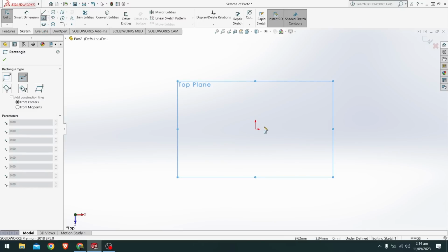I am going to select the center rectangle. Since the center rectangle needs a center, here we see the red x and y directions. You can also see the annotation of a view, which is the top view, and this is the x-axis, and this is the z-axis, which annotates the drawing angle of what we are drawing, which is very important and should not be ignored.